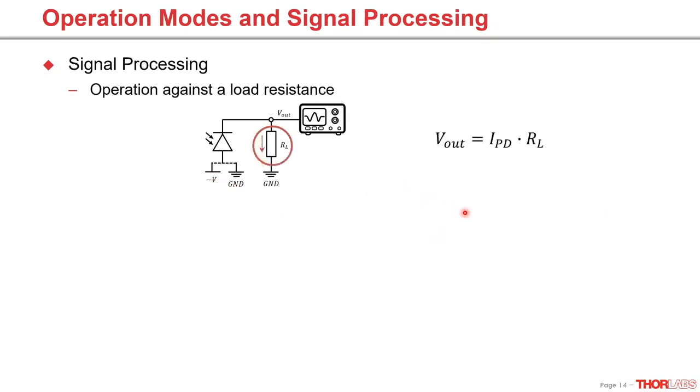However, the value of the resistance must be chosen carefully. If it is too low, the frequency response is better, but the signal is very weak. If it is too high, the input resistance of the measurement device will additionally load this resistance, the noise will increase, and the bandwidth gets lower. For best matching, the load resistance should be 50 ohms, when the signal strength allows a measurement.